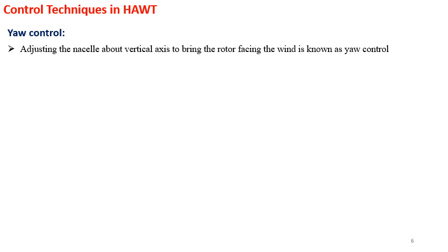Most wind turbines are yaw active or yaw controlled. That is to say, as the wind direction changes, they will track the changing direction of the wind and they will face the wind. In this case the motor rotates the turbine slowly about the vertical axis so as to face the blades into the wind, and the area of the wind stream swept by the wind is then maximum.